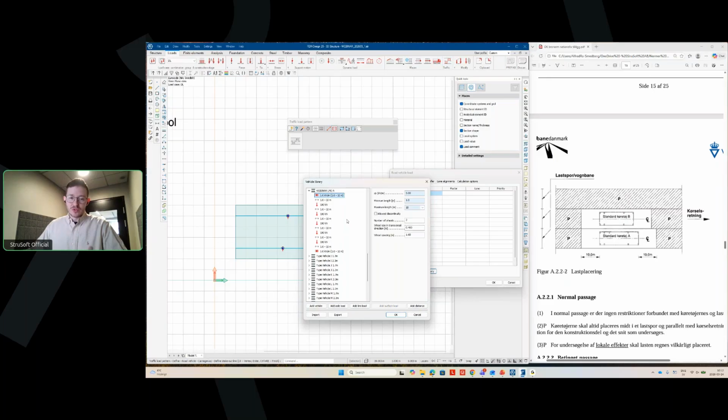And then when you do the vehicle yourself, you will, of course, have to find the exact values. But for the first one here, this is the first interesting option that we have. You get to set a minimum length and a maximum length as well. And here we come into the topic of parametric vehicles. What I mean by that is that for the distributed load for the LM3 vehicle here, there is no set distance. It is simply dependent on the position of this system in the middle. So it can, in theory, be any length.